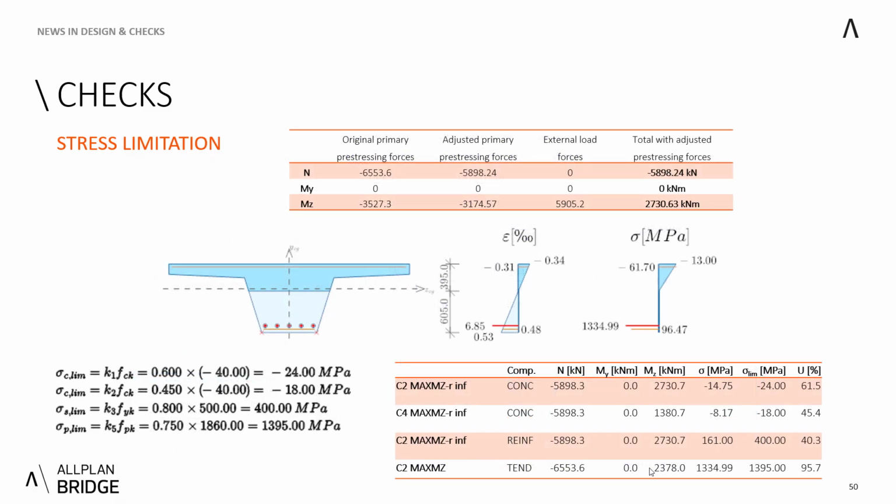Moreover, we cover this also with R sup and R inf coefficients, meaning this lower and upper value of the pre-stressing force, which for the post-tension type of tendons which we have is, I believe, 0.95 and 1.1, and I believe 0.9 and 1.1.